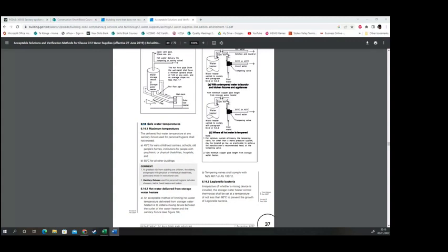Probably for this one is okay, but for that valve one and the cylinder one, it'd be better to have at least two possible reasons. Because it's kind of like, what's your approach? You go there, water's coming out of the valve on the roof. What do you do? Do you initially climb up on the roof and change it? Maybe, but maybe you try something else first, like adjusting the pressure reducing valve, or checking the temperature. Then you didn't have to climb on the roof. So that was your last resort.